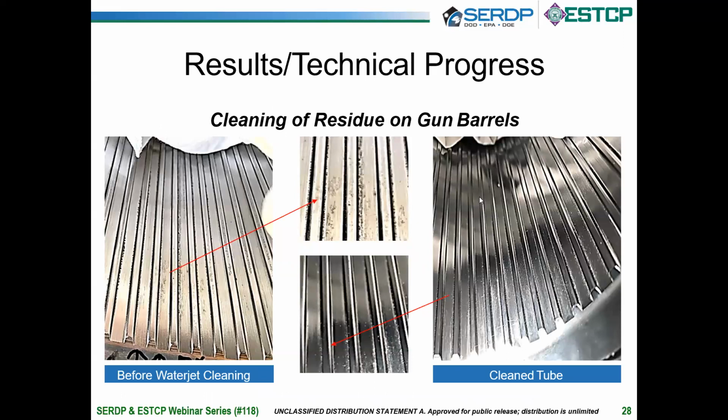And for the other methods that we're using for waterjet, the weapon systems may have whatever residue on them, whether it be the steel or the chromium coating, and it's absolutely essential that the tube be clean before any kind of process where you put on a refractory metal, whether it be chromium or any other process. And the waterjet can easily clean these surfaces before another coating is put on. And we've demonstrated that on several barrels now.